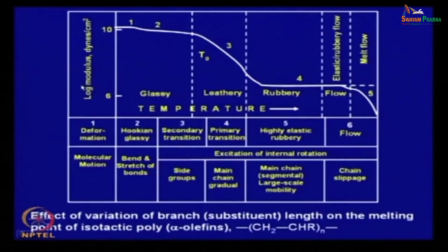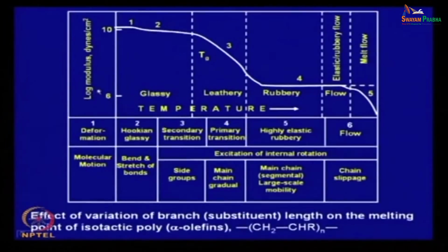So, look at the modulus. Looking at these values, one can know the stress requirement for polymer compounding, for polymer processing, say molding, extrusion, all this: how much stress is required, how much energy will be consumed for such processing. Those things can be understood from these behaviors.